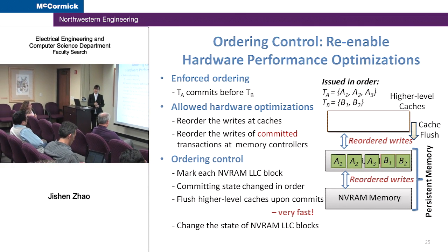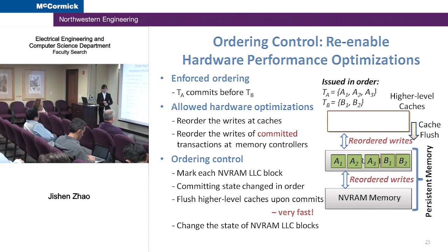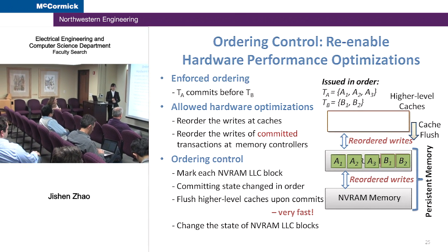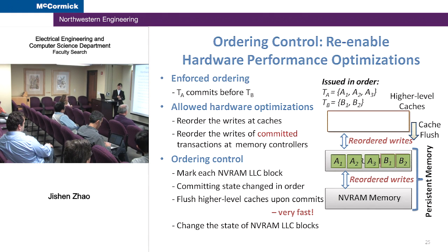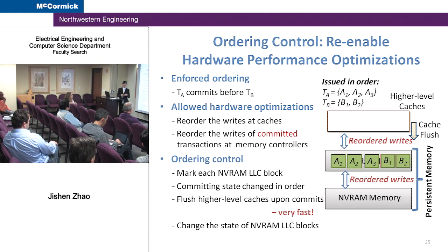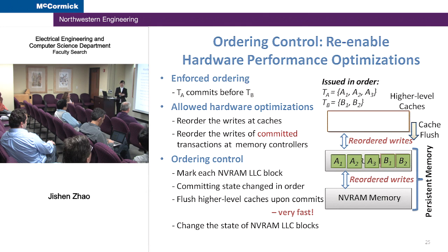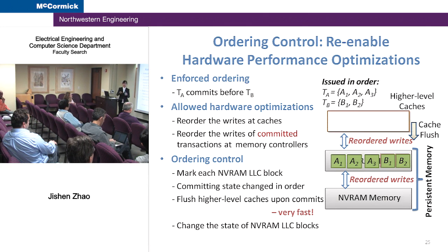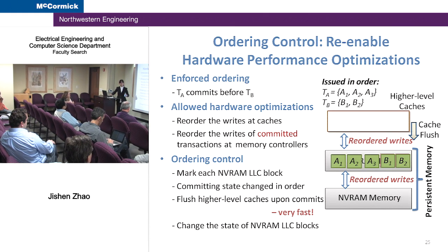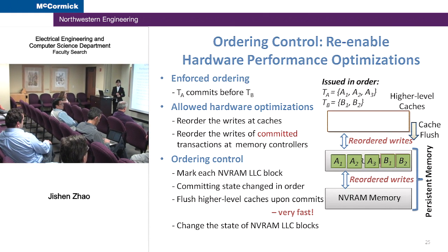Yeah, you're right. Cache is all about reuse. If it is not reused, it does not make sense. Then maybe we need some software interface to hint whether this data is reused. Then we can distinguish between different applications, or different phases in the same application, to decide whether to cache this data or flush another part of data. Maybe that part. Is it good? Thanks.